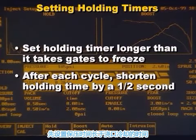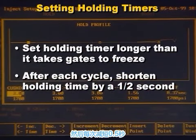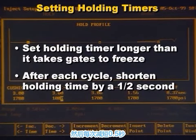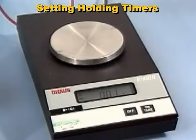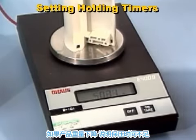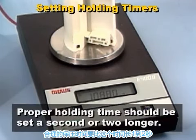Start by setting the holding timer longer than it takes the gates to freeze. Then, after each cycle, shorten the holding time by about half a second. Accurately weigh the molded part. When the part weight begins to drop off, it means the holding time is insufficient to allow the gates to freeze and discharge occurs. The proper holding time should be set a second or two longer than that.